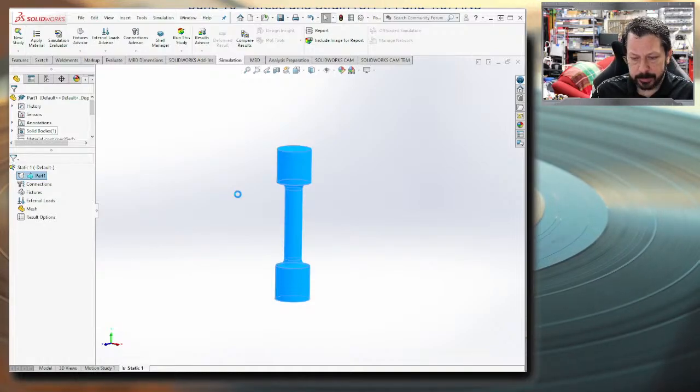And we're going to apply a force. Well, technically we are going to apply a force, but technically we're actually applying a displacement. So we're going to pull apart from the top and bottom, pulling the top away from the bottom of this tensile test specimen. While we're doing that, we're going to measure the force being applied, how much force we have to pull with, and the displacement, how far we've moved the top of the sample from the bottom. So, how much is it stretched?